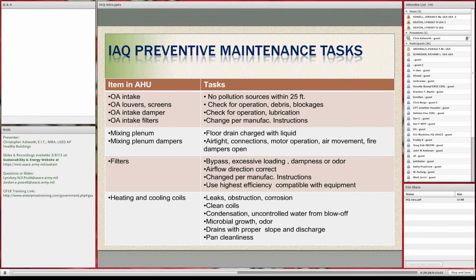Well, so here's our, what's called, for LEED existing buildings, EA Prerequisite 3, which is the management of refrigeration. You're supposed to document all the refrigerant in the building. And they thought they did, but a tenant actually had a whole subsystem that no one really knew about from years ago that actually caused a leak. And things like that of knowing what you have in your building and managing it.